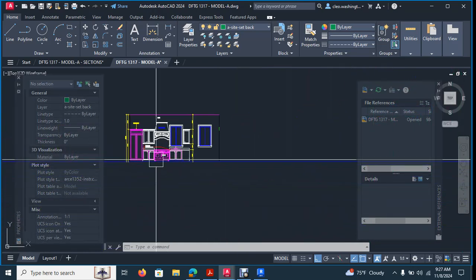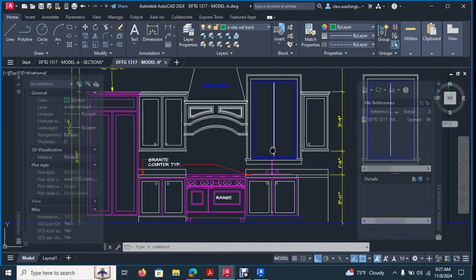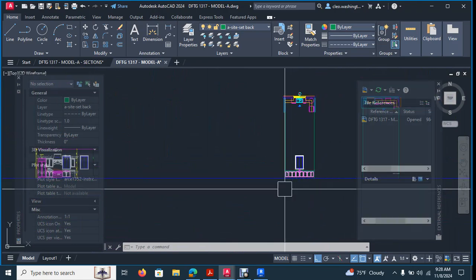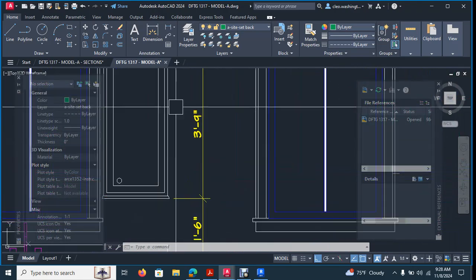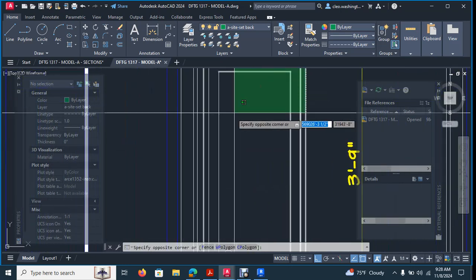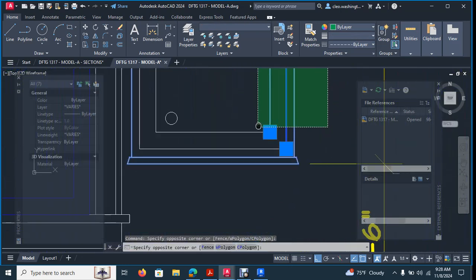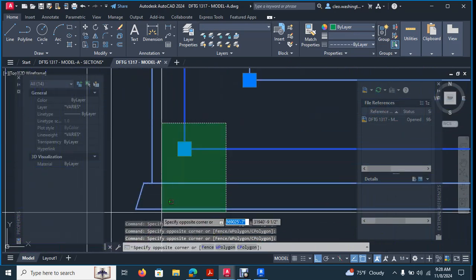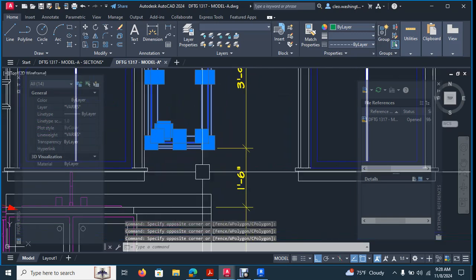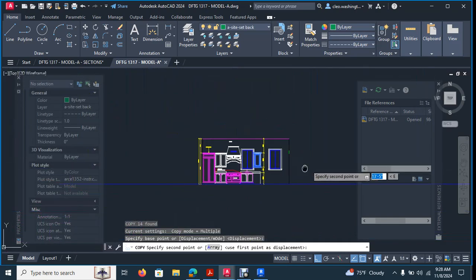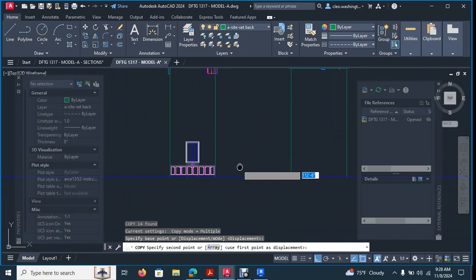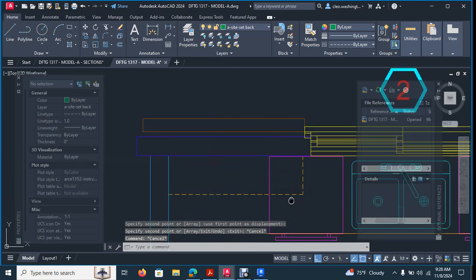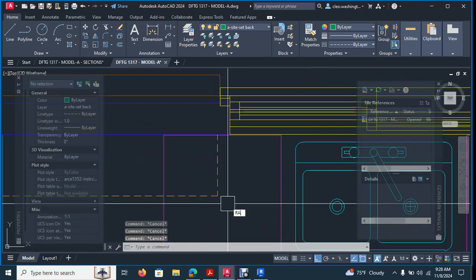Okay, now typically the upper cabinets are 1'6" above the countertop. So let's go ahead and copy these guys. Just copy this one over right here. Okay. So typically you'll have one here. Let's go ahead and project the lines down where the cabinets are, R-A-Y.